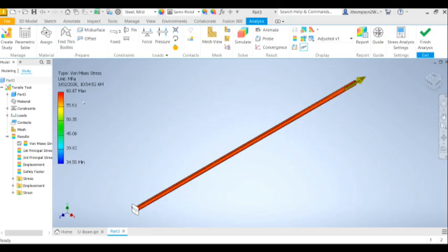Now, stress, I don't really care so much about the stress. Well, I guess we could record the stress. The stress is going to be the same for all the materials though, isn't it? Because the stress is a function of the cross-sectional area and the force. So the stress won't vary from material to material. So you could record that, but it's not really the interesting thing. The really interesting thing is the displacement, because different materials will displace by different amounts.